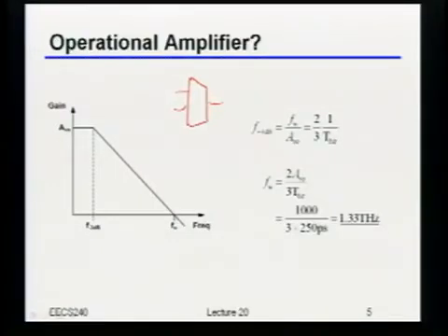Like we talked about a few times already, if I just follow my rule of thumb and set the bandwidth at 2/3 of the bit period, and I need a gain of 1,000, remember, that's AV0 right there, then I can quickly calculate the gain bandwidth product that I need. 2/3 of 4 is about 3 point something.